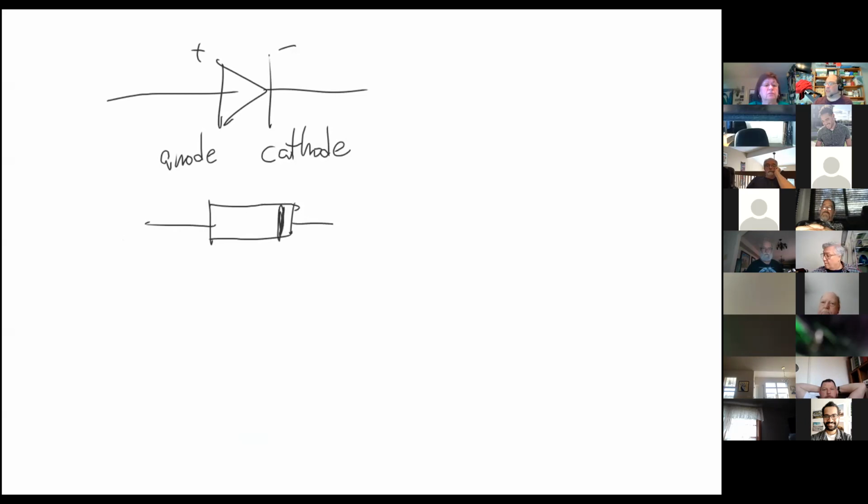If you look at it physically, there's a stripe on the cathode end of the diode, indicating the negative terminal. Notice it even kind of looks like a sideways minus sign. The important thing about a diode is that it will only conduct current in that direction. If you try to run it backwards like this, unless it's a very special kind of diode, it doesn't allow it to flow. So it's a one-way device, which is really profound.